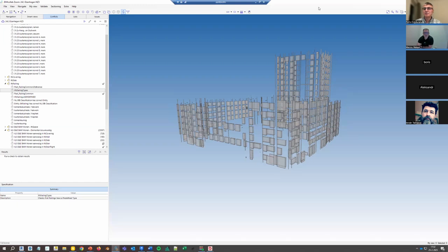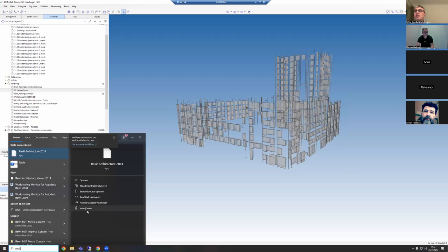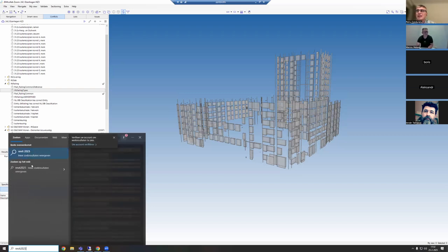Let's see. The latest Revit, yeah, I'm still using 2024, but probably the problems remain the same. Some shafts don't get exported. I think that shafts are just openings, so if they are exported, I'm not quite sure. Might be because he is using the default exporter from Revit. That could be an issue. And maybe if you install the GitHub export IFC, like a Revit to IFC export, it would fix that.